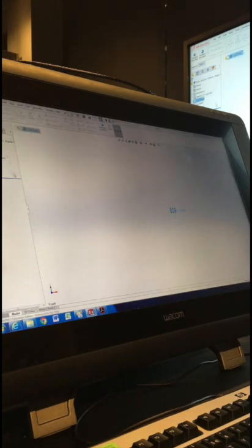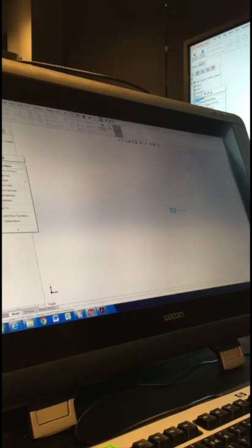If you just left click on the front plane, you see that little shortcut bar come up, where you've got some icons: sketch, show, zoom, and normal to. Or if you right click, you'll get a full menu with some other options. What I'd like you to do is click on each of those planes and press show. Then on your screen, you should be able to see the planes in the middle area of the viewport.